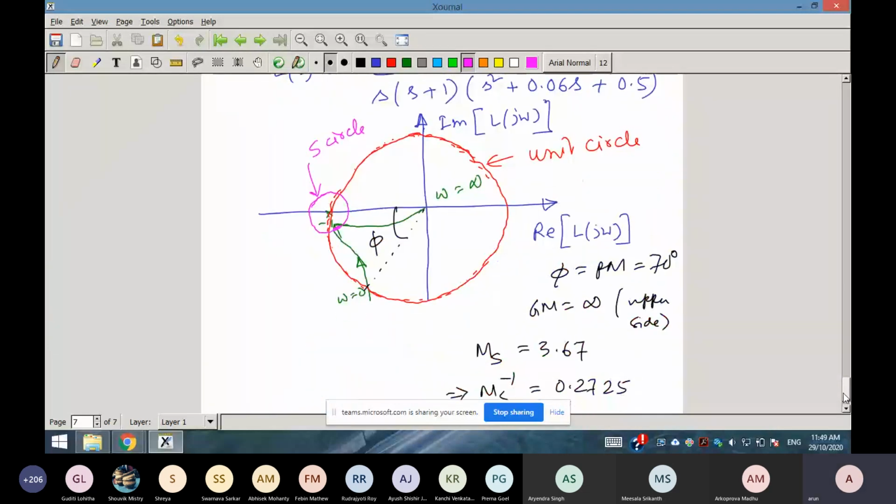Those classical engineers who still believe in classical margins will say, your sensitivity circle radius is large, but how to guarantee that gain margin, phase margin is good?